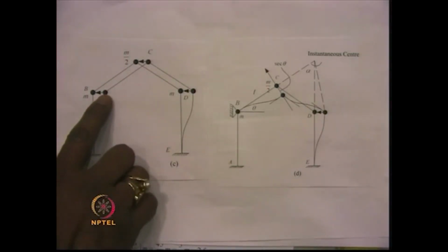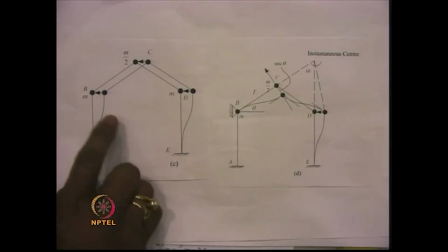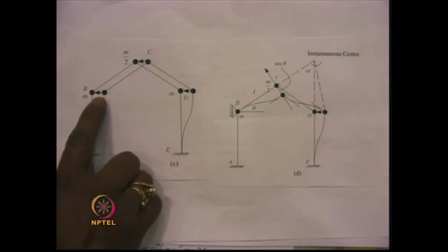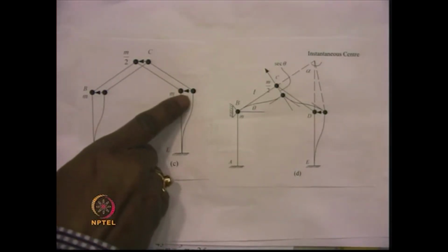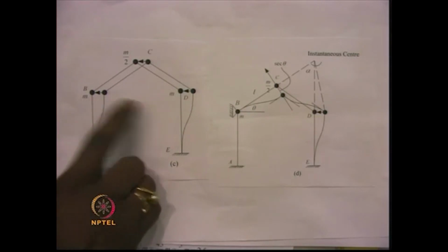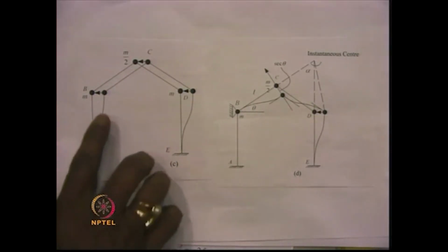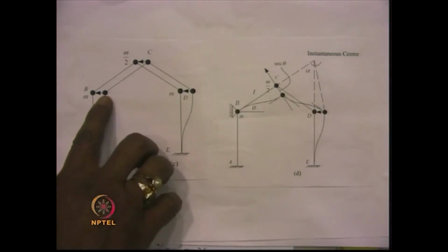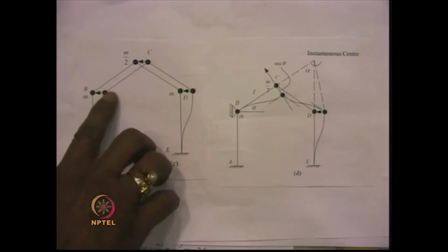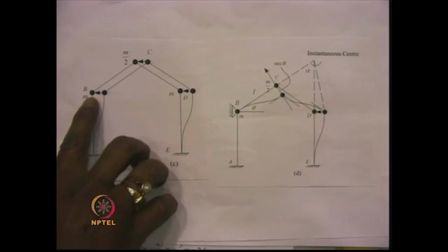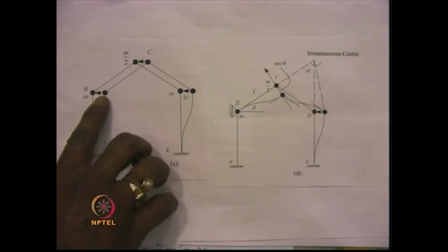The displacement is given such that a unit acceleration is induced, and that acceleration will be in the opposite direction to the direction of the motion. So, the unit acceleration is induced over here, unit acceleration is induced over here, and unit acceleration is induced over here because of this displacement. The mass times the unit acceleration, that is m into unit acceleration, will be the inertia force that will be induced due to the unit acceleration provided over here.